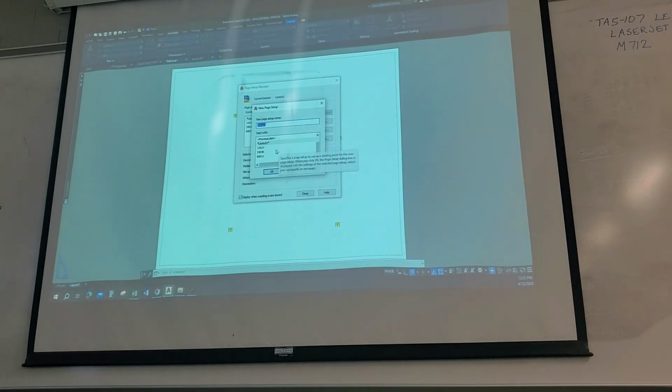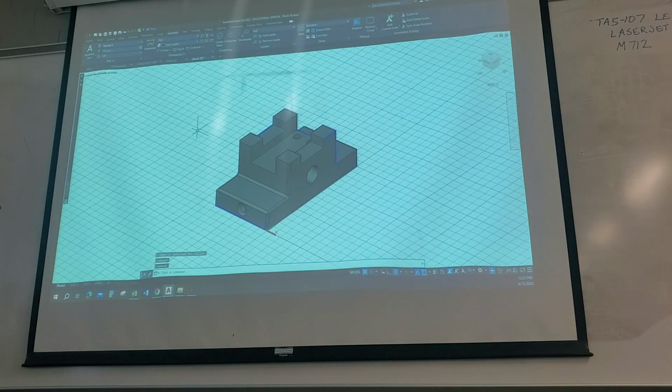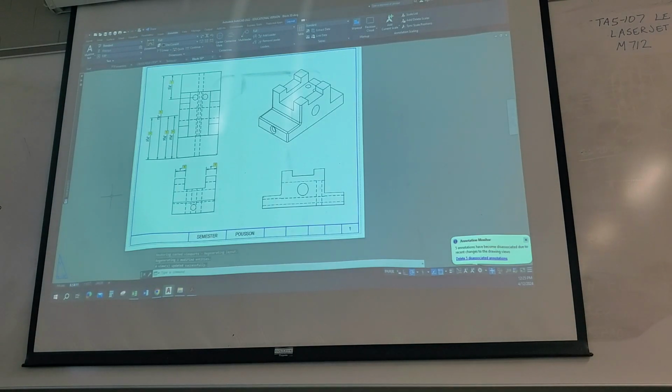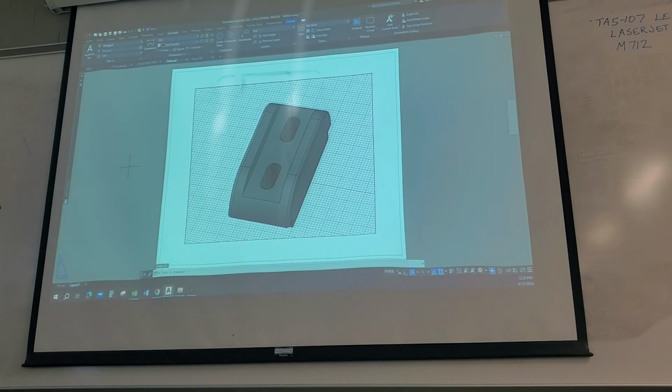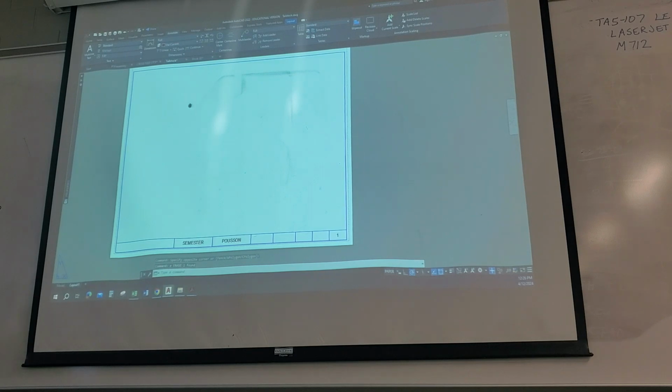So are we gonna send you the 3D version and the 2D version? Yep. Okay. I'm gonna select that 8.5 by 11, set current. I don't have a border and title block on this one, so I'm just gonna come over here and steal it real quick. Control-C, 0, 0. This dude. Control-V, 0, 0. Bam, there's my border and title block. So once again, on this one, we do not need a viewport.